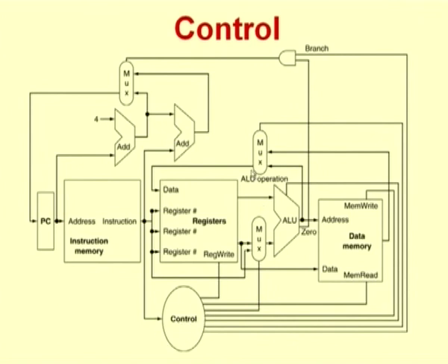Okay. And if you look at the output of the multiplexer, the output of the multiplexer is now fed back as data to one of the registers that need to be stored. Okay. Now where will this control information actually come from? How will the control decide? Again you can see that information also has to be decided based on the instruction that is to be executed. So instruction information will also have to be fed into the control unit. Okay. So you can see that using a control unit and with the help of all these multiplexers and so on, and with logic you can have a complete path that can be designed. So we will stop now, take a small break and then come back and look at some of these details.